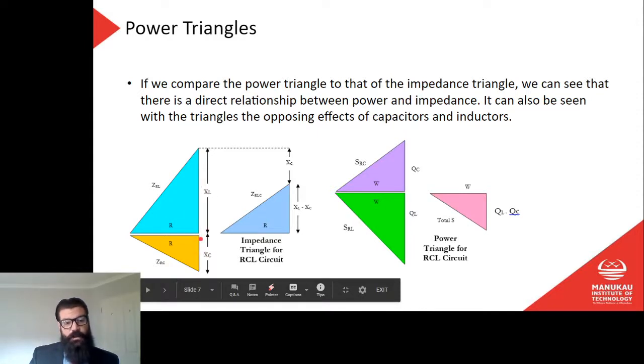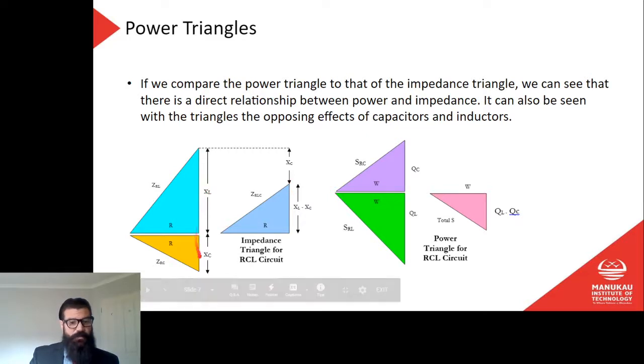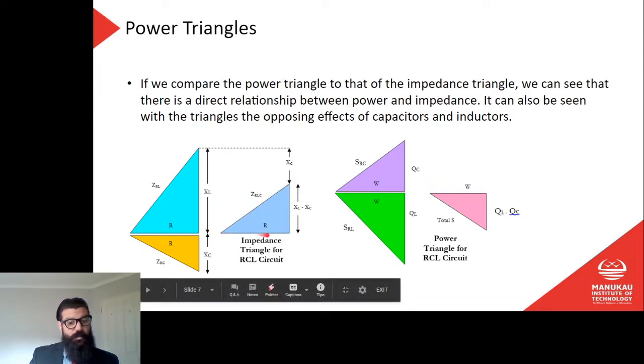If I subtract the capacitive reactance from the inductive reactance, because they're both on the vertical axis, then I get one triangle which will have this side here be XL minus XC. The R side does not change, and then obviously Z, the impedance, will change. My phase angle now gets smaller. So actually this is a little hint on power factor correction, right? Because if I added more capacitance, then XL minus XC gets smaller and smaller.